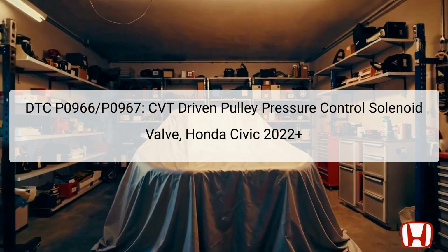These detected issues impact the continuously variable transmission (CVT) performance by affecting the pressure regulation necessary for effective power transfer. The vehicle's transmission control module, TCM, is responsible for interpreting the signals from the solenoid valve and storing the respective DTC when abnormalities are detected. Understanding the role and location of these components is essential for effective diagnostics and repairs.